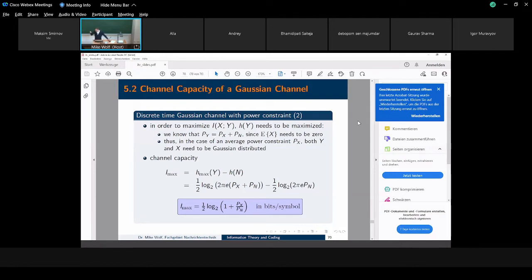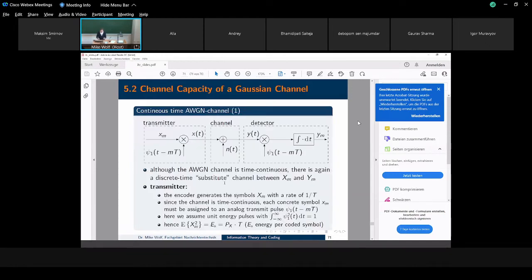And today, now we come to this question, what about bits per second? We have to basically map a continuous time AWGN channel, which is also referred to as a waveform channel, because any real-world medium which I can use for transmission, a copper cable, glass fiber, radio frequency channel, whatever, is an analog medium.